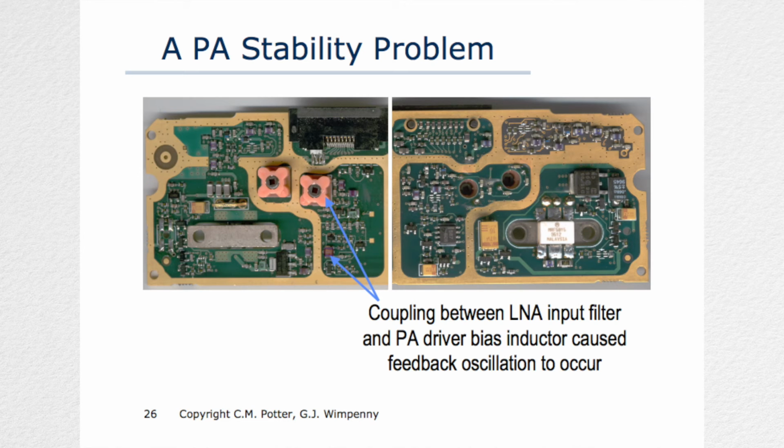In this particular case, it was provisioned hoping it wasn't needed, and then it turned out to be absolutely needed. So it was quite good to have got the provision in the first place. So we're looking at both the receiver input and the transmitter output end of the product here. There's quite a large power transistor which is able to produce about 7 watts of RF in transmit mode. That gets coupled to a contact here onto which a VHF antenna is connected. There's also an auxiliary connector here, which is the car kit connector, and there's a RF connection over there.